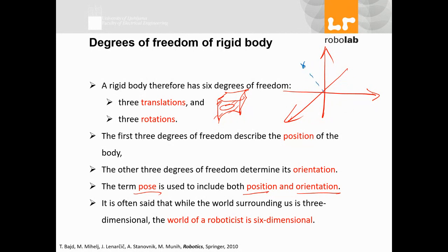We want to figure out what is the position of that point, and that's why we need X, Y, Z. For people working on pure math or students working with elementary math, it's kind of weird. 6 degrees, what does it mean? We have only 3 degrees. If you look at a point not as a point but as a solid object, in that case you really need that. And you care not just about position, but the pose and the orientation of the object.